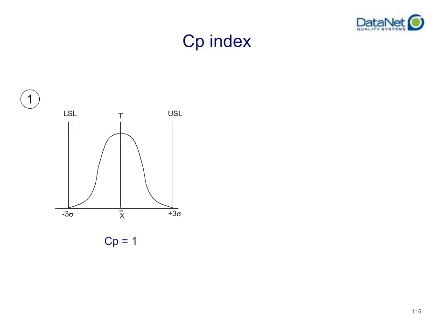If your CP equals 1.0000, that means that in an ideal world where you were producing most of your product right on your center line, 99.73% of your data would fall within specifications, within plus or minus 3 standard deviations from your center line. Plus or minus 3 standard deviations from your center line would be 99.7% of your data.